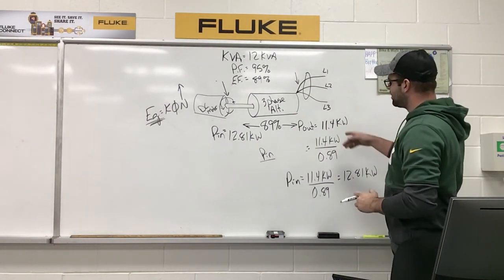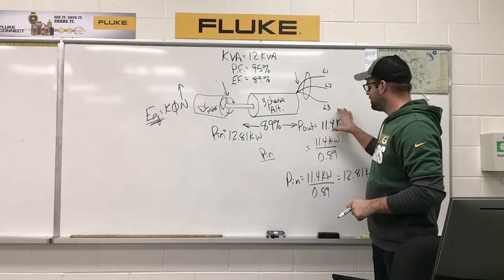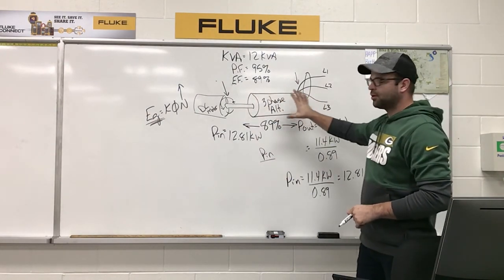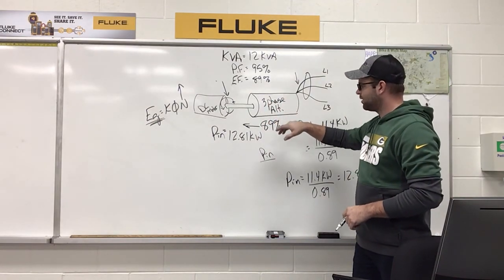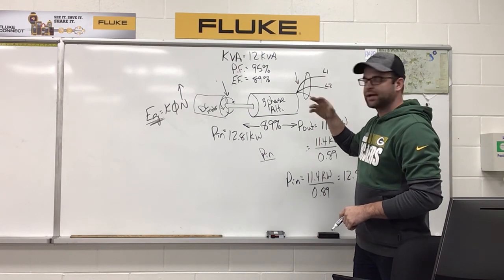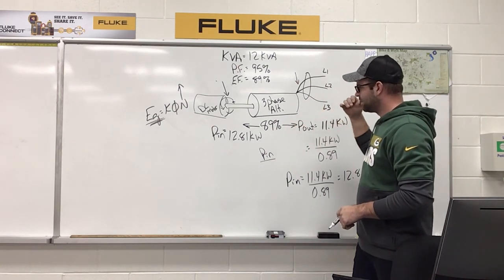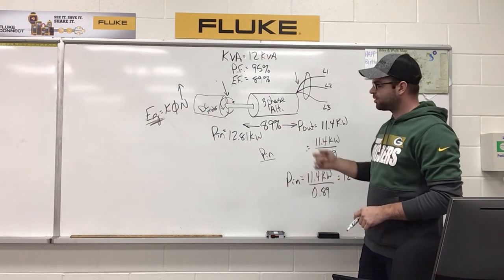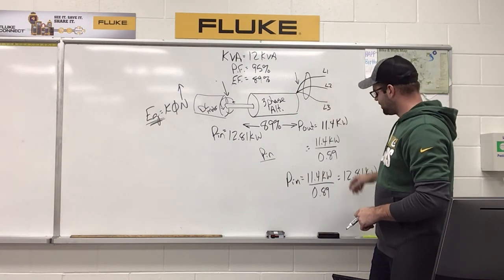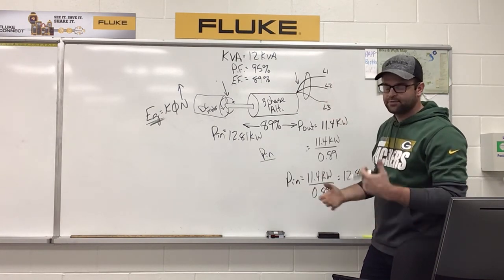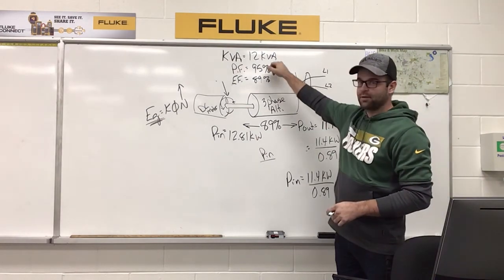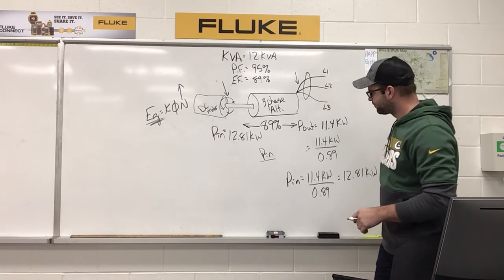So the smallest value in here should be what your power output is, because there's losses through your alternator, whether they're mechanical losses, heat losses as you go through, I squared R losses, so it's going to end up being smaller. And then obviously depending on what's connected to it, if you've got an inductive or capacitive load, your output kVA will be larger than that value.